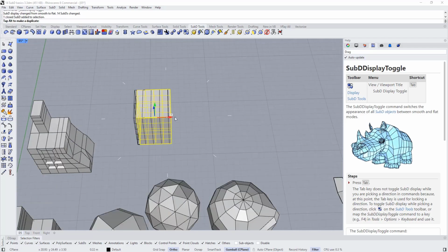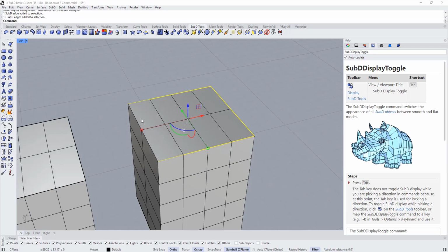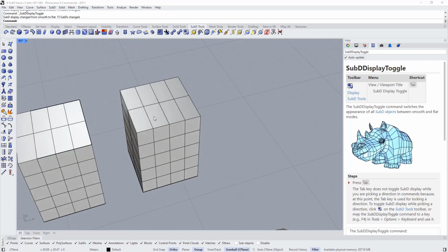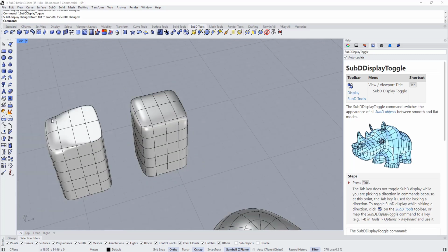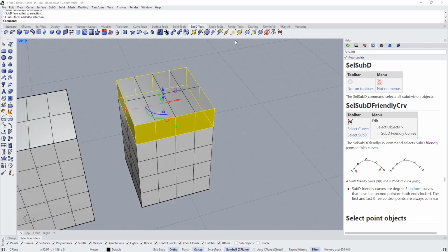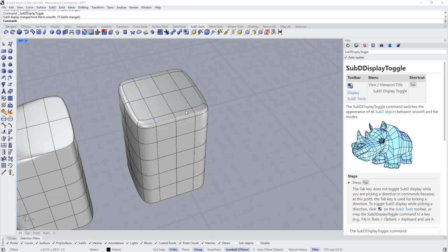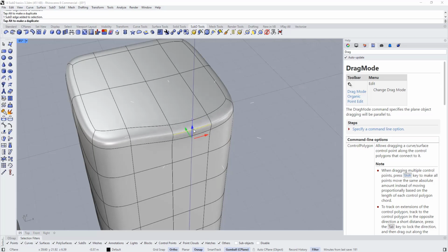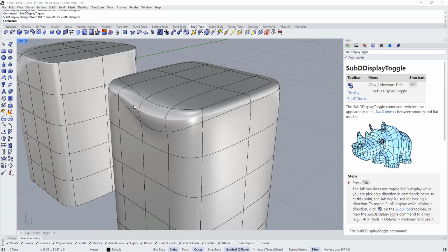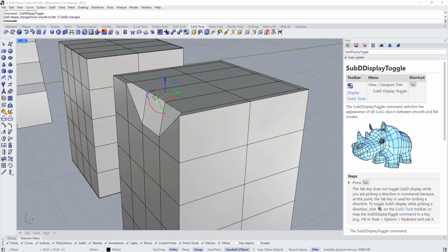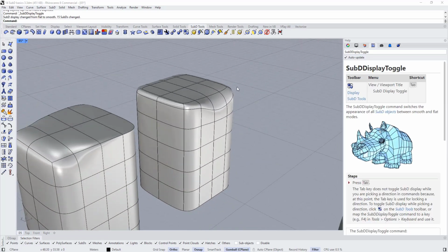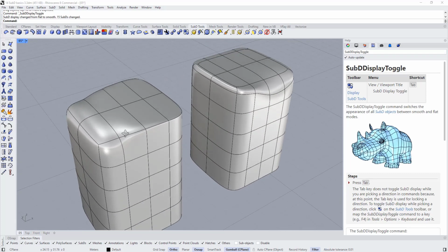And this tool is actually very useful. In Rhino 7, let's set this again to smooth. Now it's completely smooth. To achieve the same kind of crease here, you would double click here, select this boundary, and insert some kind of edge here and start moving this down to get different values of roundness. So this would save us a lot of work and will reduce the file size, because you do not have to create the same amount of edges or faces.